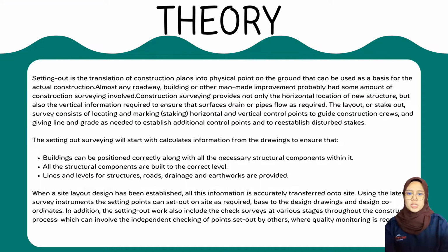Next, I'm going to share with you the theory of setting out. Setting out is the translation of construction plans into physical points on the ground that can be used as a basis for the actual construction. Almost any roadway, building, or other man-made improvement probably had some amount of construction surveying involved. Construction surveying provides not only the horizontal location of new structures, but also vertical information required to ensure the surface drains or pipe flows as required.